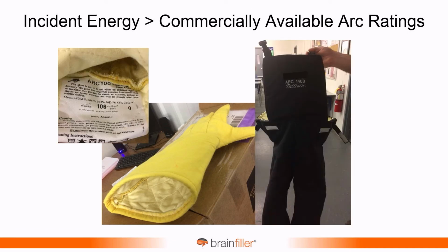First off, I want to mention PPE. The arc ratings have been going up considerably. This one on the right, that's actually my hand holding it up. It almost stood up by itself. This is an arc rating of 140 calories. And so arc ratings continue to increase, but not everybody has access to this kind of PPE. And you can still have incident energy levels above these values.